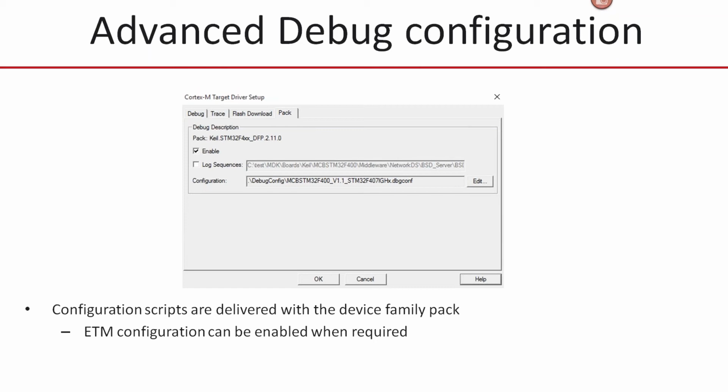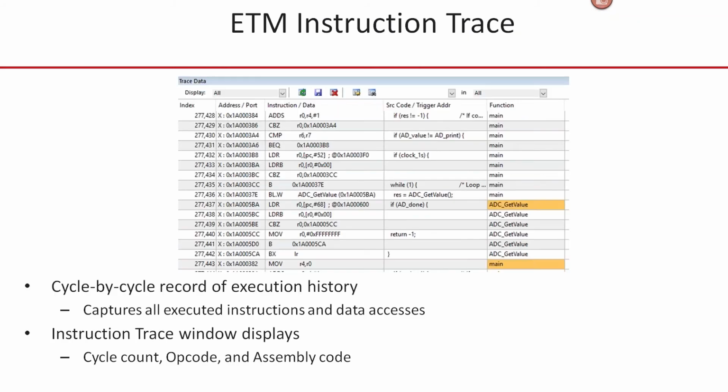Once we have the trace port configured, we can now get a streaming trace from the Cortex microcontroller to the debugger. So this gives us timestamp, assembly and C-level tracing. And it's important to note that there is no trace buffer within the Ulink Pro.